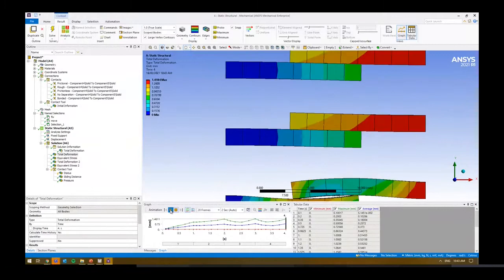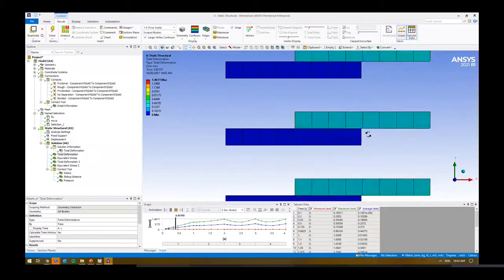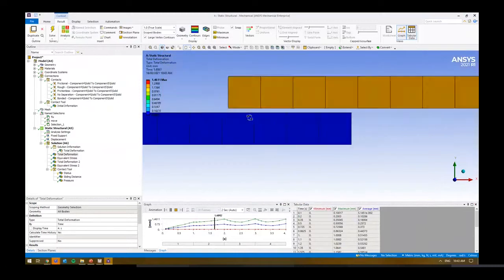and I think we've got a frictionless contact here. It's able to move. There are no shear forces whatsoever. It just moves across, moves up and down. As it comes back down into contact, contact is established and it's able to slide back.